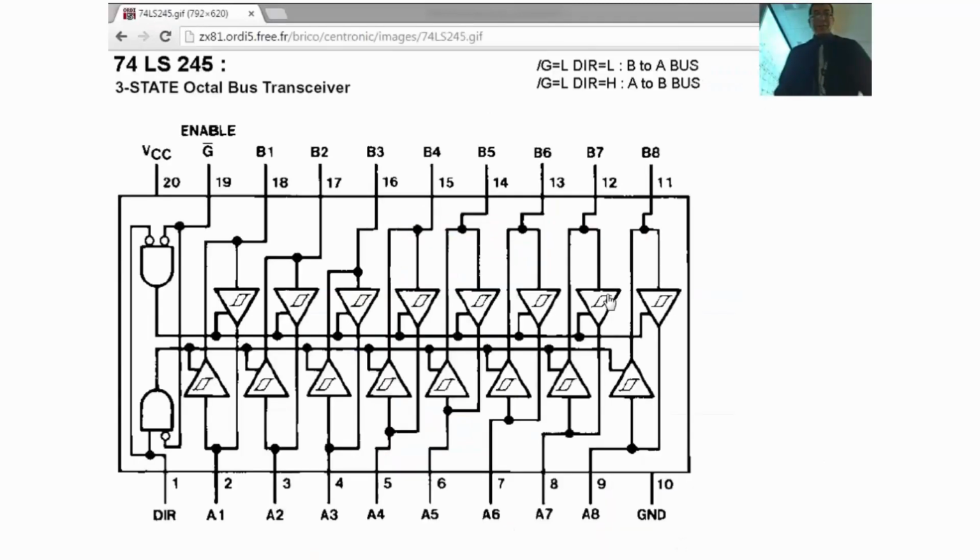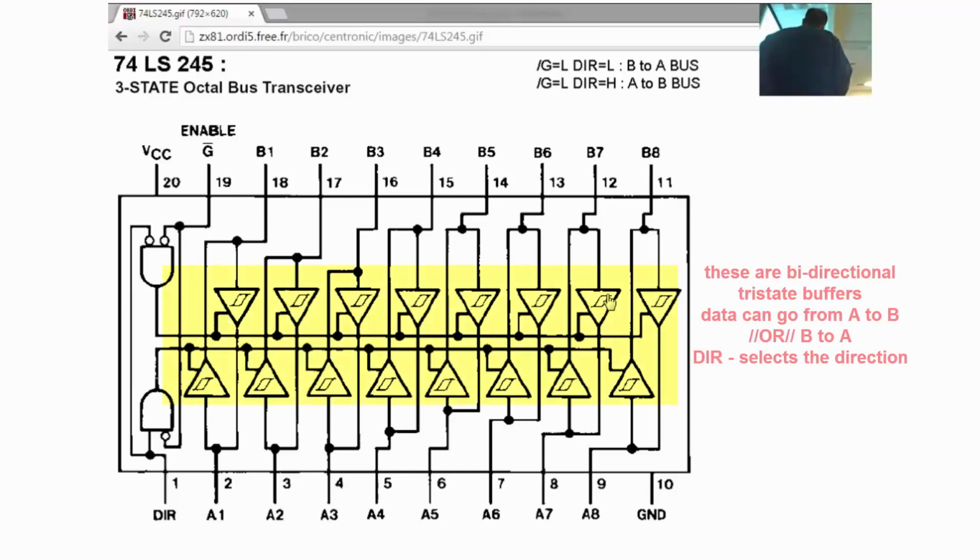Okay. So the 7400 series are chips that you can hold in your hand. They're actually TTL logic levels, so a 0 is 0 volts, a 1 is 5 volts. A lot of interfacing devices need that voltage to work. You want to connect your microprocessor to something to turn lights on or off, or control things. You can use this to drive that device.